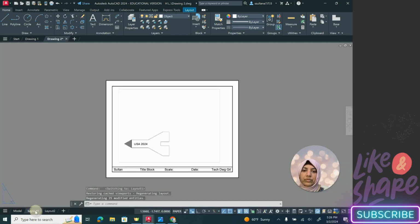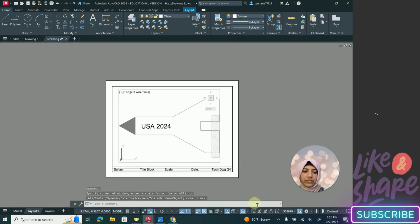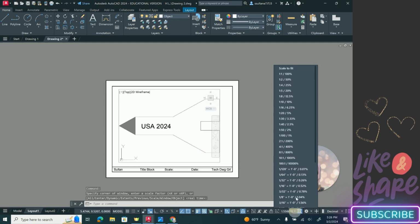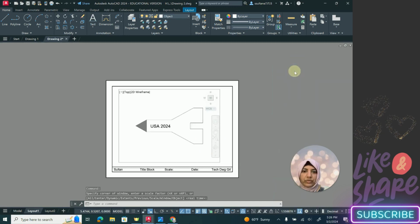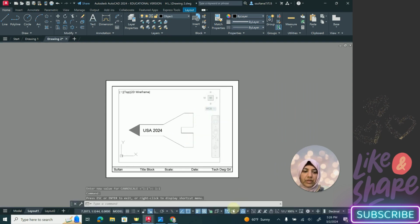Go to layout, and it's visible in the viewport. Double click inside the viewport and click on zoom extents. Now go to the scale and give it 1:1, and you can use pan to move it to the middle. Exit, and then lock the viewport.